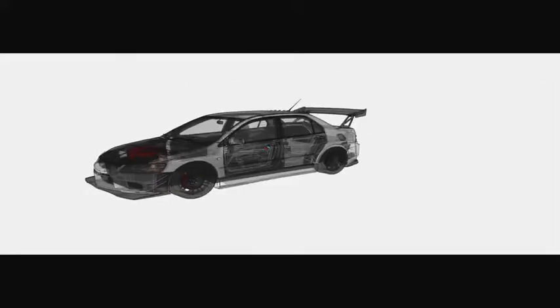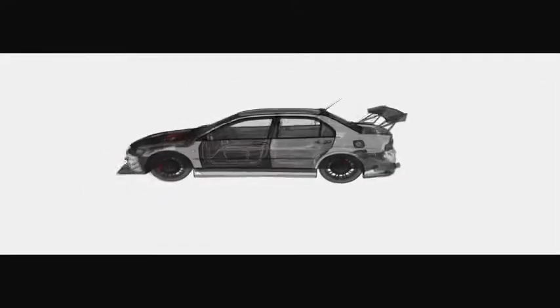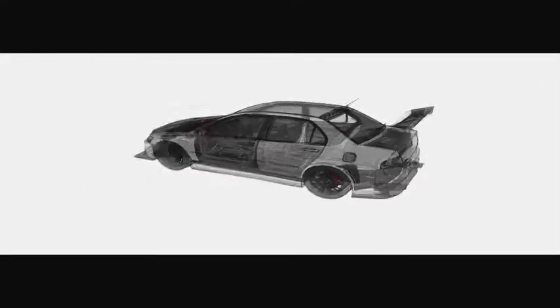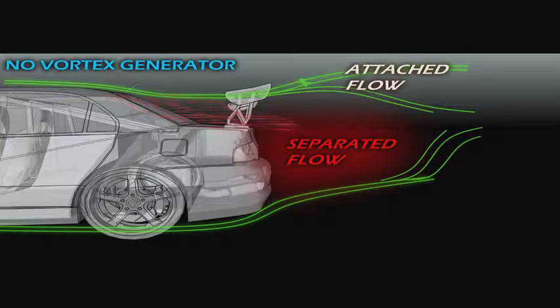The decade-old rivalry between Subaru and Mitsubishi spawned a very popular aerodynamic component that is sported on most of their production cars and has become quite a style in the automotive culture, but actually holds a very powerful automotive aerodynamic purpose. Designed to work with a rally-inspired wing, we need to understand that these vortex generators were designed specifically to work with a large spoiler or wing, not without one.